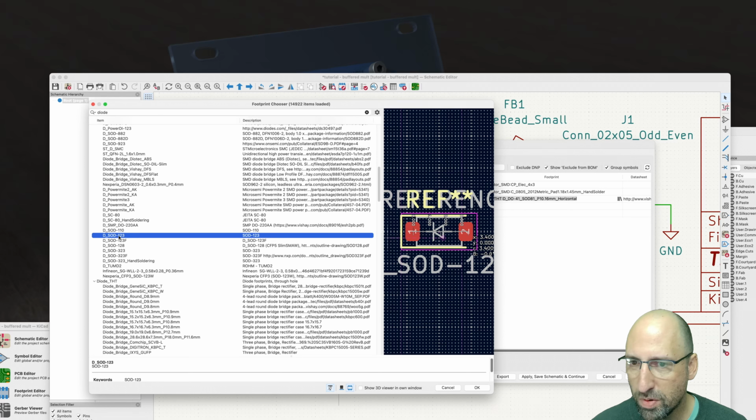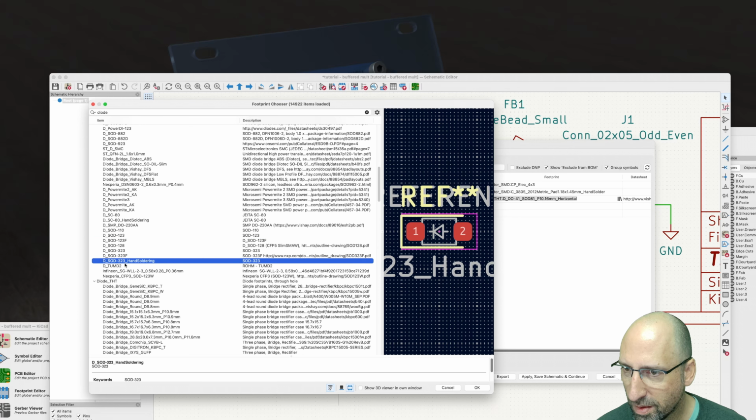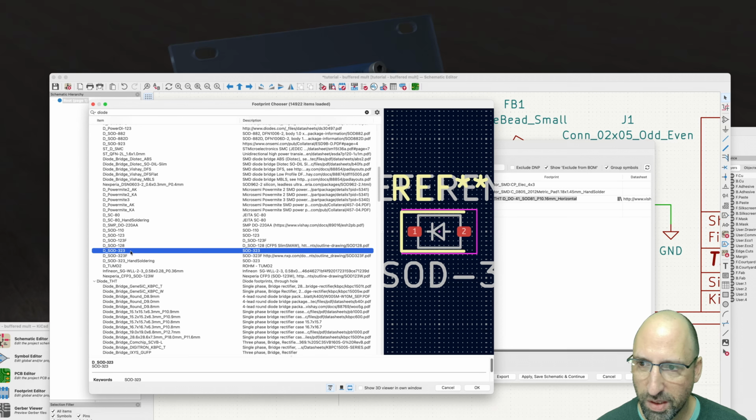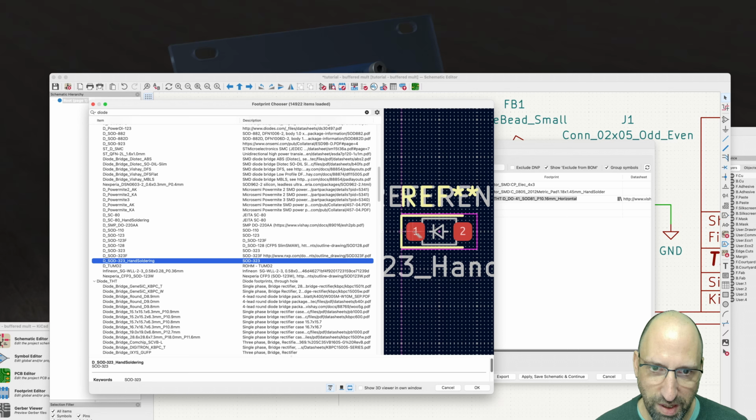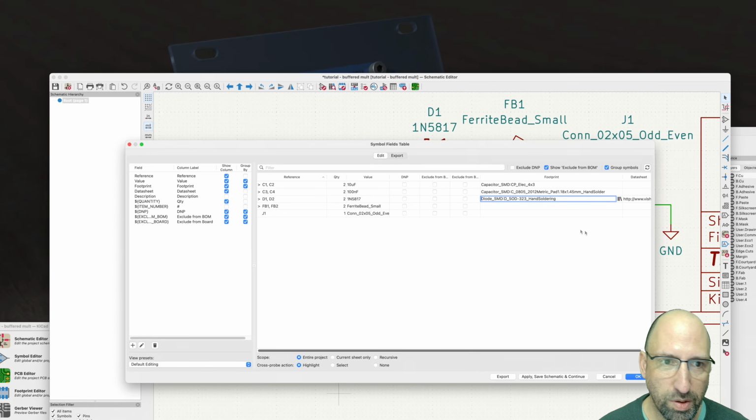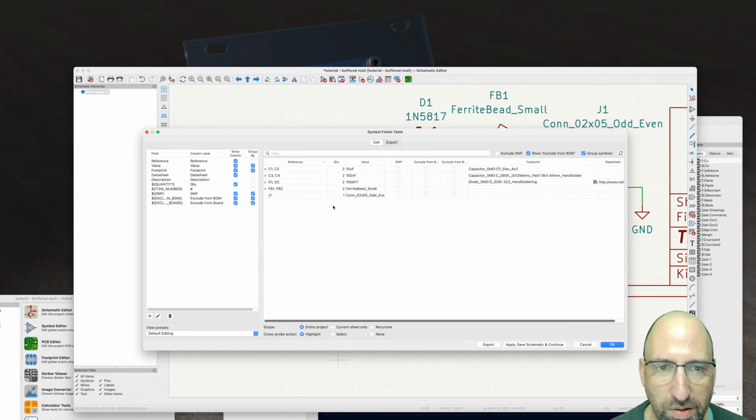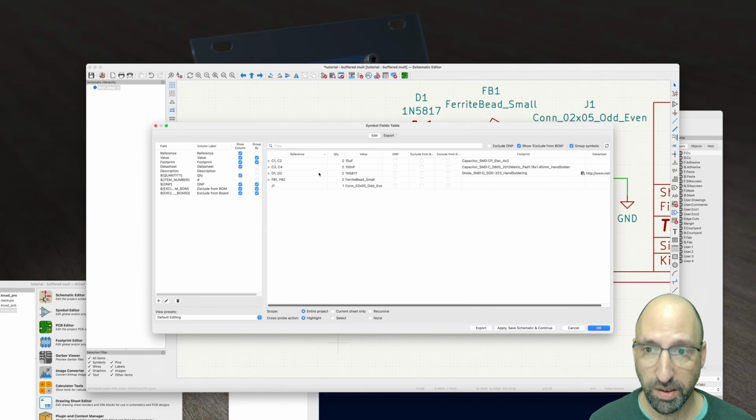And this is important when we're actually picking components, right, to solder on here. But I'm going to go with a slightly larger one. In fact, no, I'm going to go with a smaller one, but with a hand soldering option. It's just going to make those pads a little bigger. There's without hand soldering. There's with hand soldering, right? It just makes it a bit neater to work with if you're just soldering directly with a soldering iron.